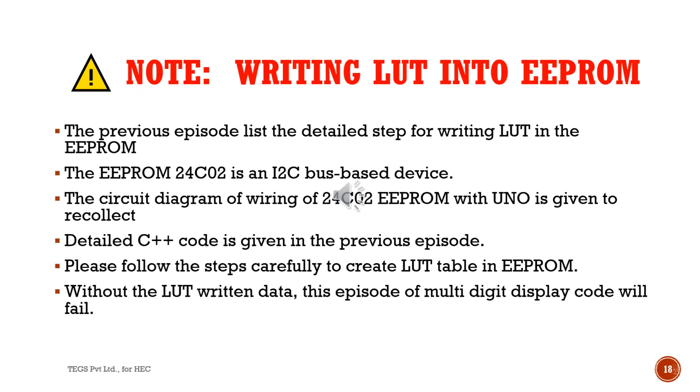Note: writing LUT into EEPROM. The previous episode lists the detailed steps for writing the LUT in the EEPROM. The EEPROM 24C02 is an I2C bus based device. The circuit diagram of wiring of the 24C02 EEPROM with Uno is given to recollect.